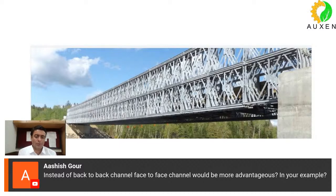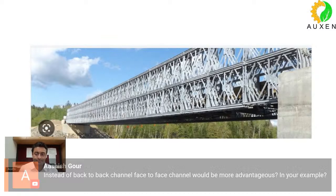So I will have my top and bottom cord, and then when I want to connect, let's say, the verticals or the diagonals, having a back-to-back arrangement will be easier with respect to connections. Yes, with respect to strength, face-to-face will give you more strength because it will give you a higher radius of gyration, but back-to-back offers better connection capabilities.